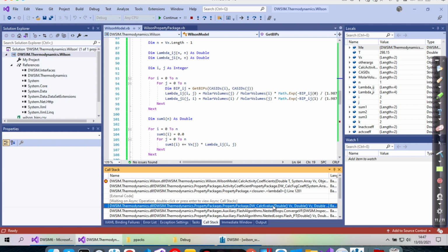And this is also very common when you have air inside the vapor stream. When you're dealing with pure water, it's IAPWS-IF97, the thermodynamics, and this works very well for pure water. But when you have some air, some nitrogen, something else, your equilibrium is not the same anymore, and it's not your data that is wrong; it's your model.